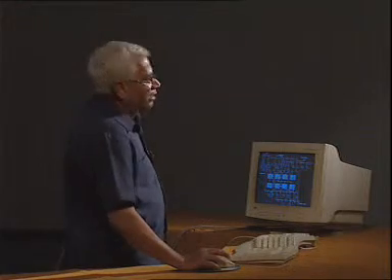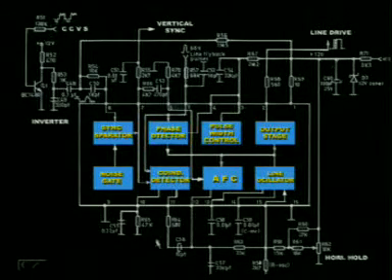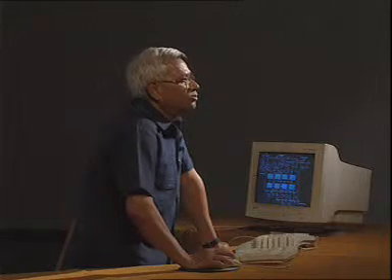But where are these sync separator, oscillators inside your television? In present television, all these stages are inside an IC. We have taken out one circuit which contains the sync separator, noise gate, line oscillator, etc. The composite video signal enters this IC through this inverter transistor and goes to the sync separator. The horizontal means line drive and the vertical sync are sent to other stages.